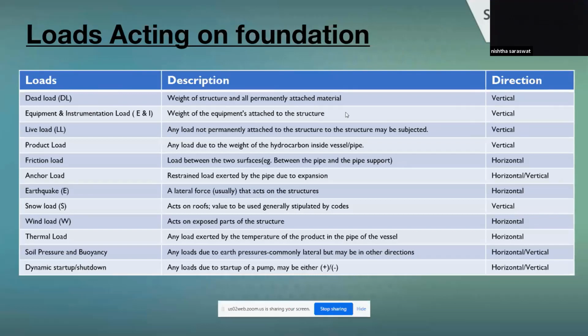And in the various load combinations, we take, for example, dead load plus live load, dead load plus live load plus wind, with various factors, and also in addition extreme cases, extreme environmental loads such as earthquake loads or other environmental loads.